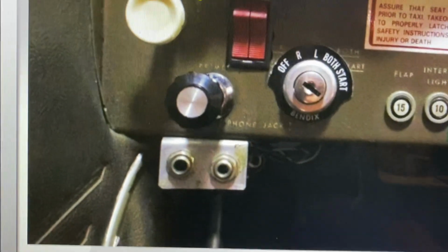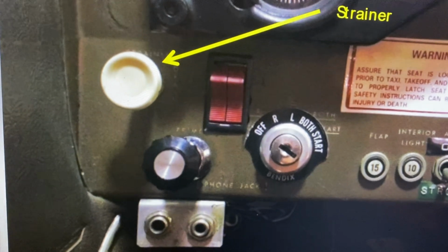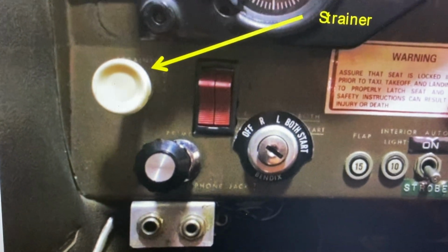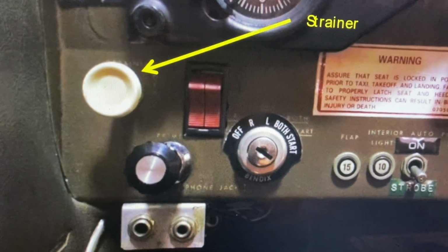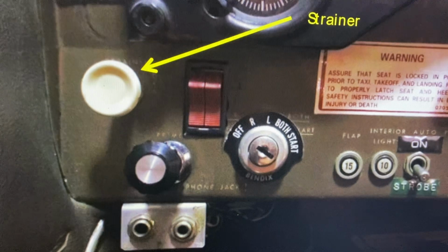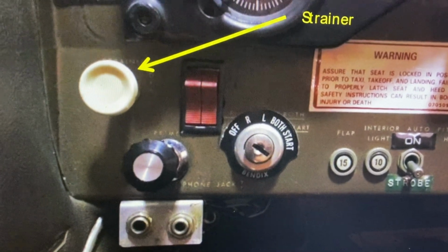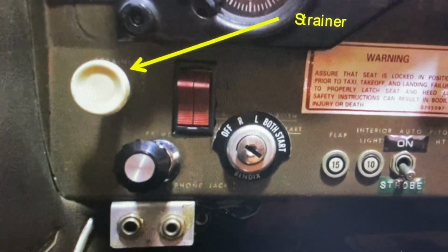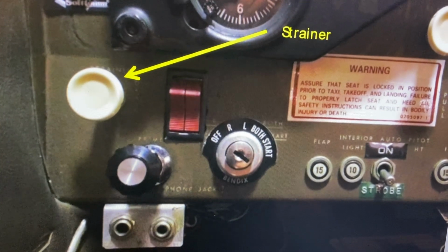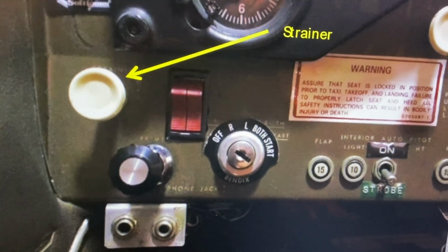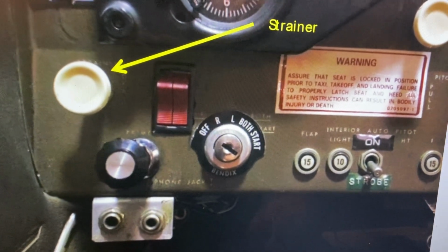But the way these airplanes are set up, one of the magnetos on the engine fires one spark plug in each cylinder, and the other magneto fires the other spark plug in each cylinder. The reason is redundancy. So if you ever lose a magneto, you still have at least spark in every single cylinder. And if you ever lose a spark plug, the other spark plug will still be firing because it's running off a different magneto. So it's a redundancy thing. To where if you had everything running off of one magneto, then if that magneto was to fail, now you're looking for a place to land. Well, this, you can still fly the airplane.